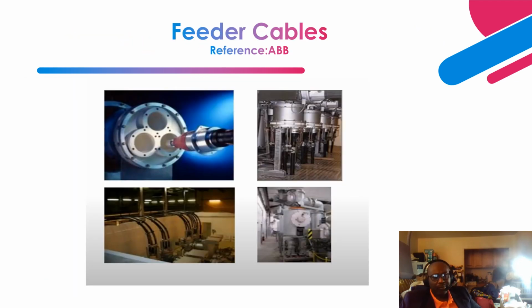Next is the feeder cables. Like I made mention, you have a cable compartment where the feeder cables are installed. Phase A, phase B, phase C are installed in here. Some of the manufacturers have made installation easier. They have plug-and-play connectors, where you don't have to do a lot of work terminating the cable. You can easily plug it in and install it.